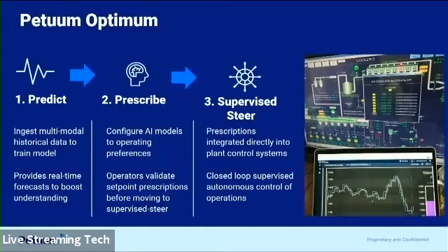So now, if we can predict well, the question is, how do we operate better? We need to find in the state space the optimal combination of set points. For example, in this case, we have 3 control variables, and then we have around 10 manipulated variables. So what is the optimal condition in order to drive more energy recovery while maintaining the product temperature? That's the question at every, let's say, 5 minutes. In this case, the application is running every 5 minutes.